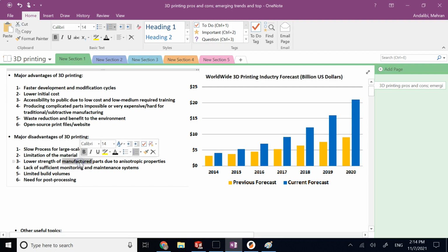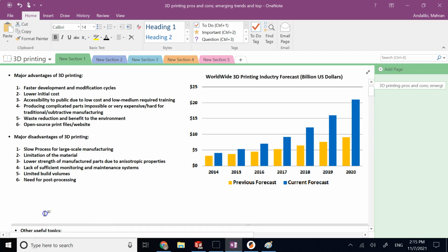The progress that 3D printing has made in that area is far less than in the other areas so far. There are some talks about annealing 3D printed parts, but because plastics are not easily annealed and you cannot do a lot of heat treatment on these, the fusion of the layers together will typically cause deformation of the printed parts and loss of tolerance. So that's a very hard area to improve easily.